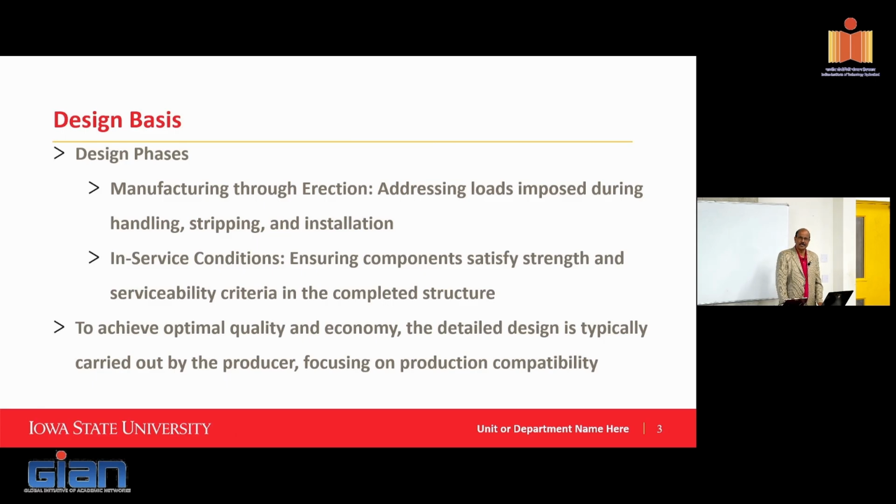So when you go into the design phases, obviously normally we do the service conditions as well as the strength conditions, but most importantly now you have to look at the manufacturing phase all the way to the erection, because you have to address the loads imposed during handling, stripping, and installation, right?